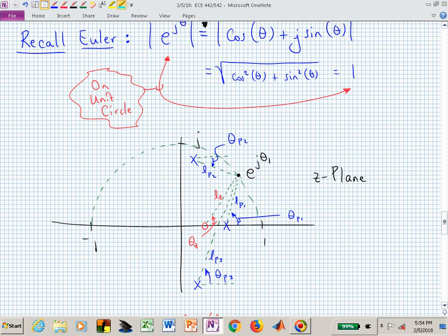And now we can draw our diagram in the z-plane, consistent with how we set it up in the s-plane, except now we're focused on the unit circle. Now we want to evaluate this at a distance 1 away from the origin. And in this case, what's the order of that system that I'm generically illustrating in this plot? What's the order of that H of z?